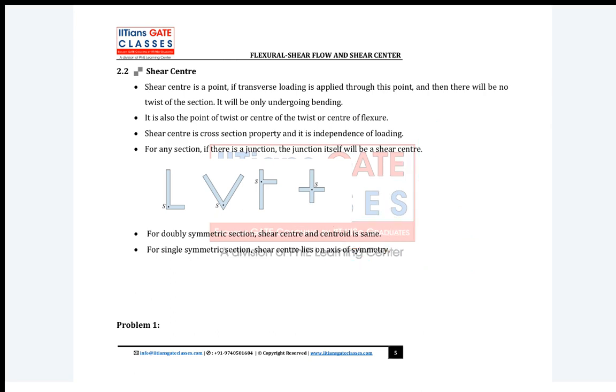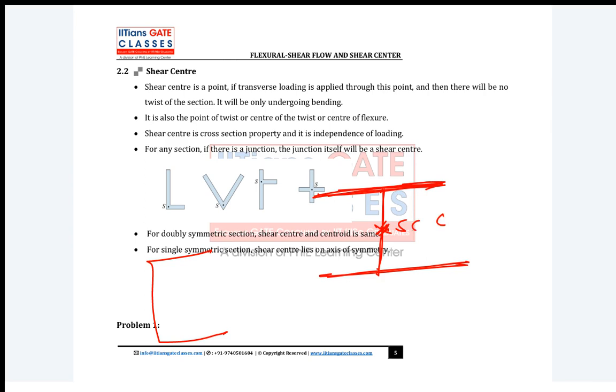So you see in many places your beams are I section, not C section. Clear? Why are these I sections, not C sections? For an I section, we can make a symmetry, right? So your shear center and centroid will be the same. Clear, this point, guys? Or you can see some places you will see T section also. I will explain the advantage of having T section or L section also.